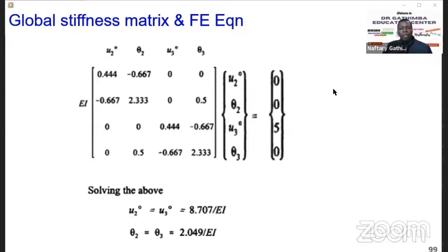To get the moment at the nodes, we need stage 7 or 8 of the finite element analysis stages, the recovery stage, where we calculate the derived quantities, the moment. So we go back, extract element-wise, and calculate the elemental nodal quantities.